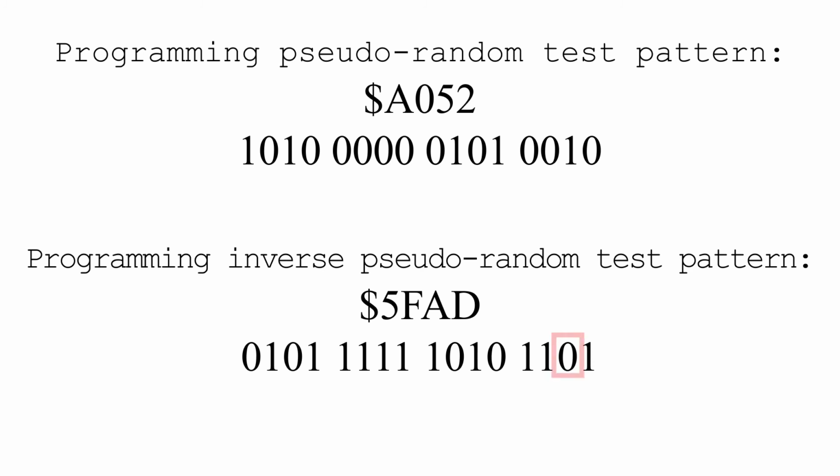The issue was an open in IO1, which is this bit right here. Notice that in the inverse, the bit is already low. So when this circuit is tested, it won't show a fault. This is why the circuit must be tested with a specific sequence and the inverse of that sequence. I hope this was enlightening for you.